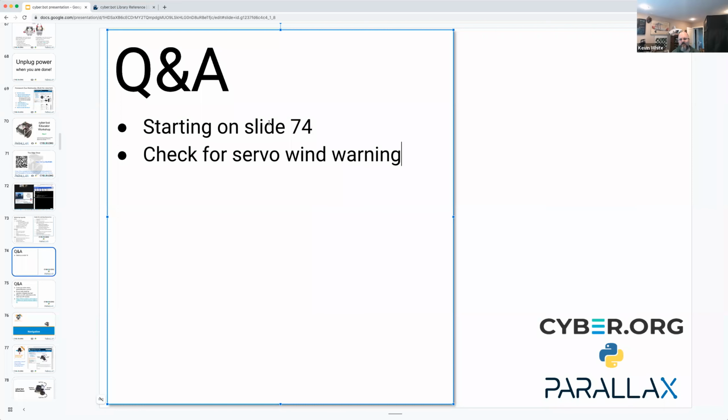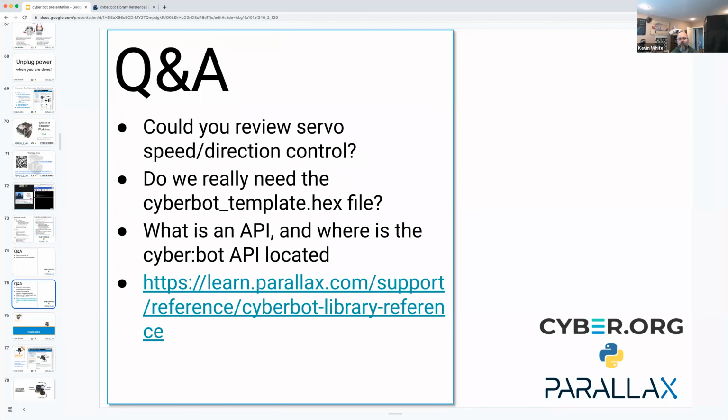I always like to demonstrate with something else how you can power things, right? Go in reverse and generate electricity that way. But with some devices, eventually VEX ended up fixing that. But on early stuff that they did, you could actually fry the controller, like a lot of things, right? You can send electricity back into the controller. Yes, because a motor is a generator. It just depends on whether it's turning something for you or you're turning it, because it can generate electricity.